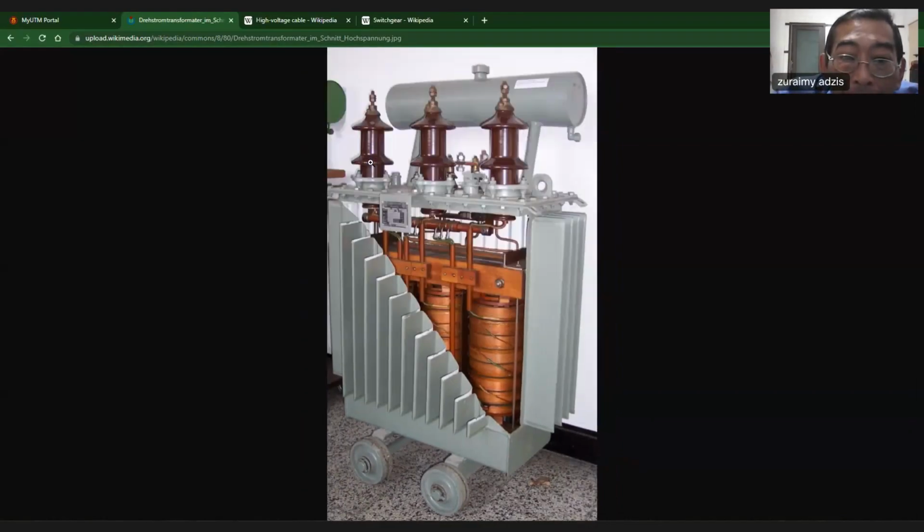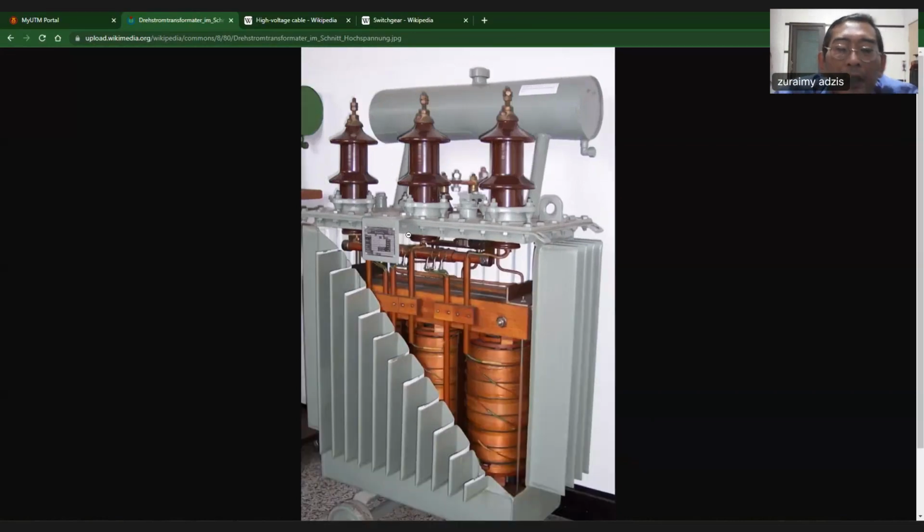This is the nameplate. Okay, as you can see there, all the details about this product are on the nameplate. And as you can see, these awkward looking fins, all right, they are actually the body or the enclosure of the transformer, and everything inside here is filled up with transformer oil. And this transformer oil, when it goes to the fins, becomes cooler because it can distribute the heat from the oil itself to the environment. So it becomes cooler, and then it goes back to the center of the transformer. So this is a cooling system, and they call these cooling fins.